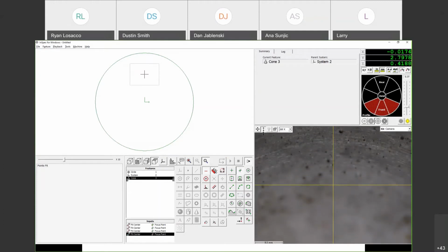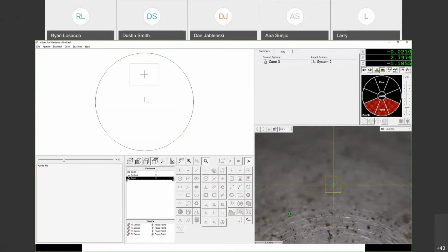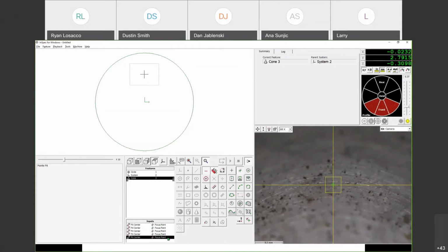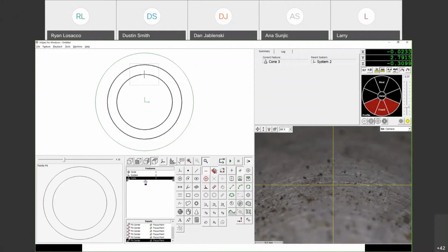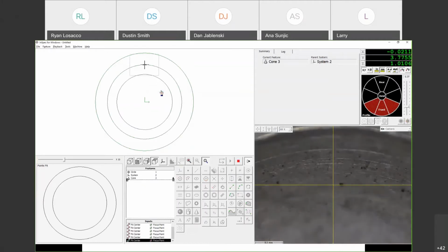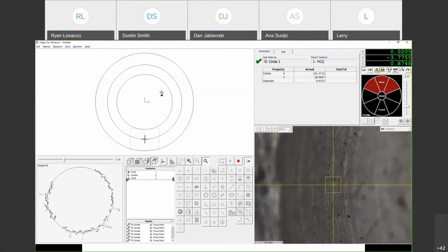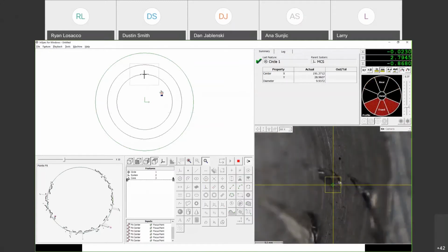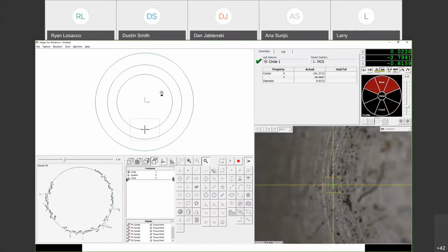Now I'm going to come lower down into the cone and take another point. And notice in my inputs, I have the 4 points here. So it's going to take those 4 points first. And I'm going to take that, and then I'm going to rotate that 5th point. Same thing. I'm going to say 90, 3 copies. And now I can right click on that cone and remeasure. You can see as it goes around, it changes the lighting that I have to that angle.